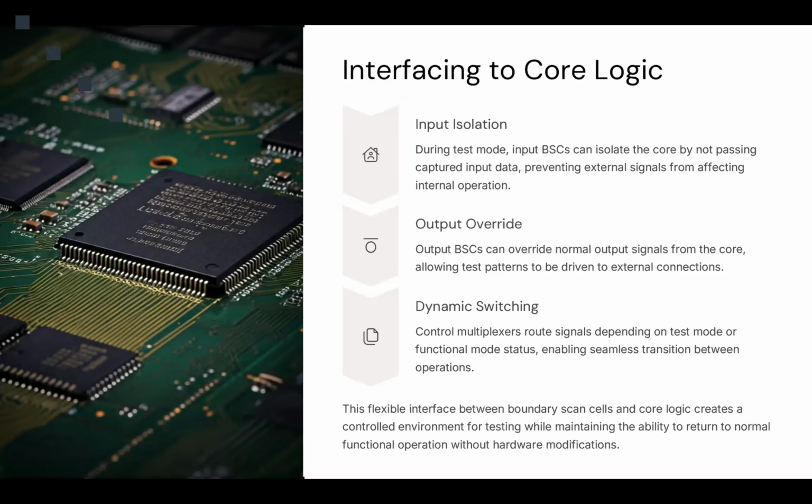When we are in a test mode, we have input boundary scan cells, and we can isolate the internal core logic from the external signals, so we don't have unintended logic behavior in our system.